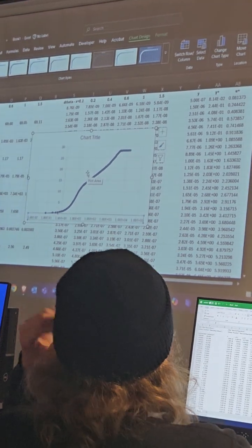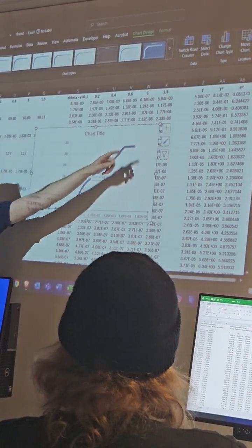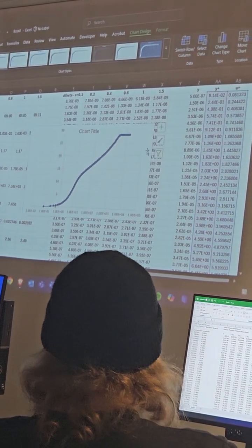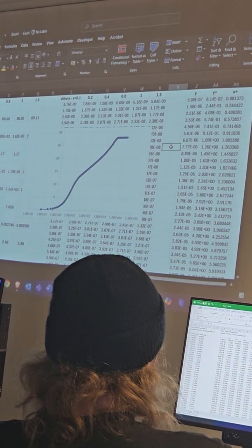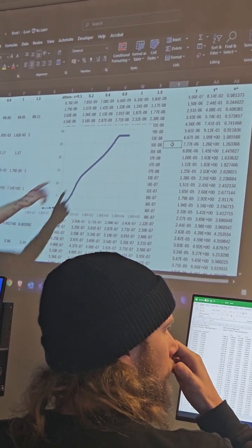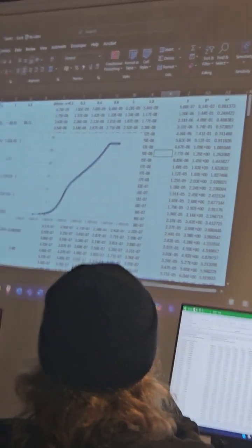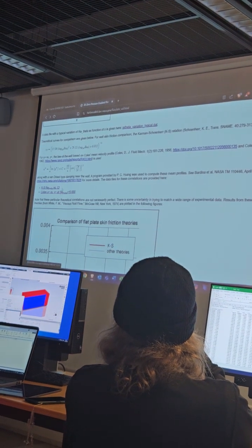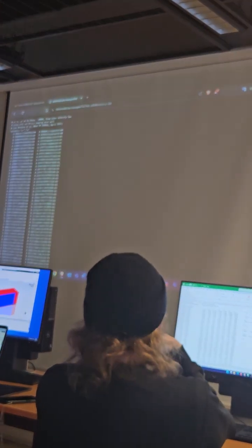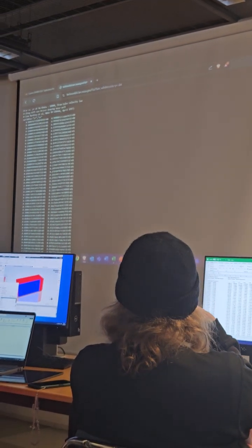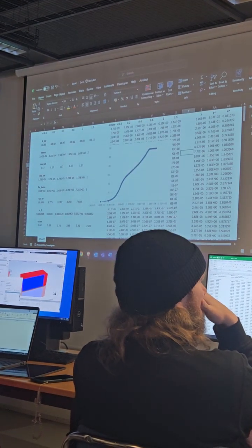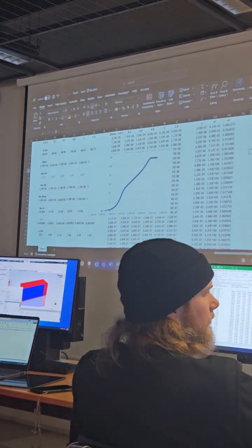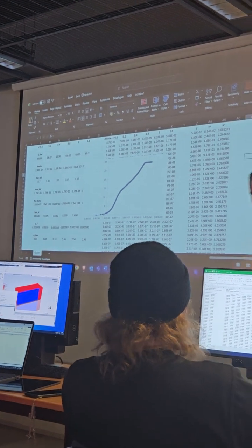You can see the different layers: the viscous sublayer, the log layer, and I'm missing the name of the last layer, the defect layer. You can also compare this distribution with the theory values. We also have on the website this kind of distribution. You can find the text file at Reynolds theta equal to 10,000 for y plus and u plus, so you can compare CFD values with the theoretical ones. Rho wall is rho infinite, it's constant everywhere. We are assuming a constant density.